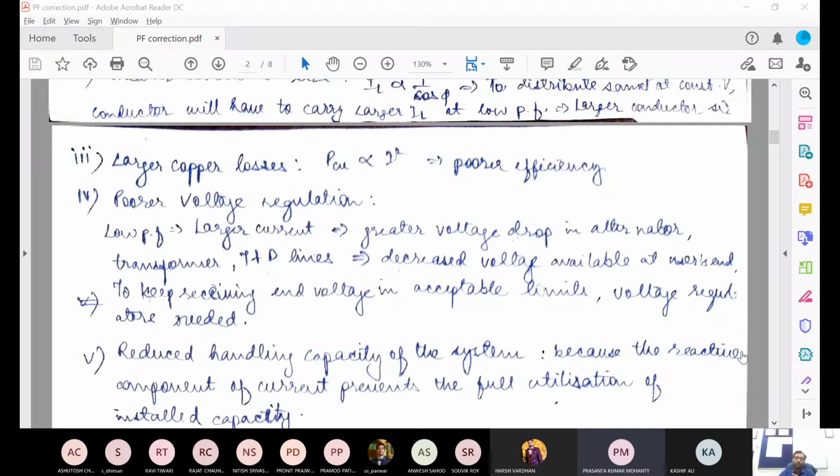That is due to distribution, that means line effects, you can tell. Load effect. Yeah, the loading ultimately is coming from there, but the voltage regulators will be placed at different places across this entire thing. Usually the substations will have a voltage regulating device so as to maintain that voltage at the proper level, and in terms of the power factor also, capacitor banks and all will be there at these substations.